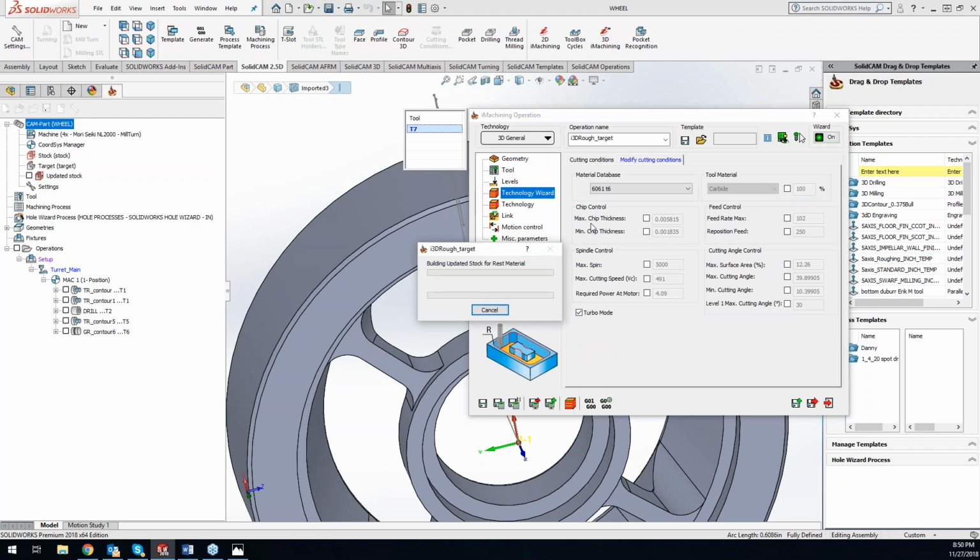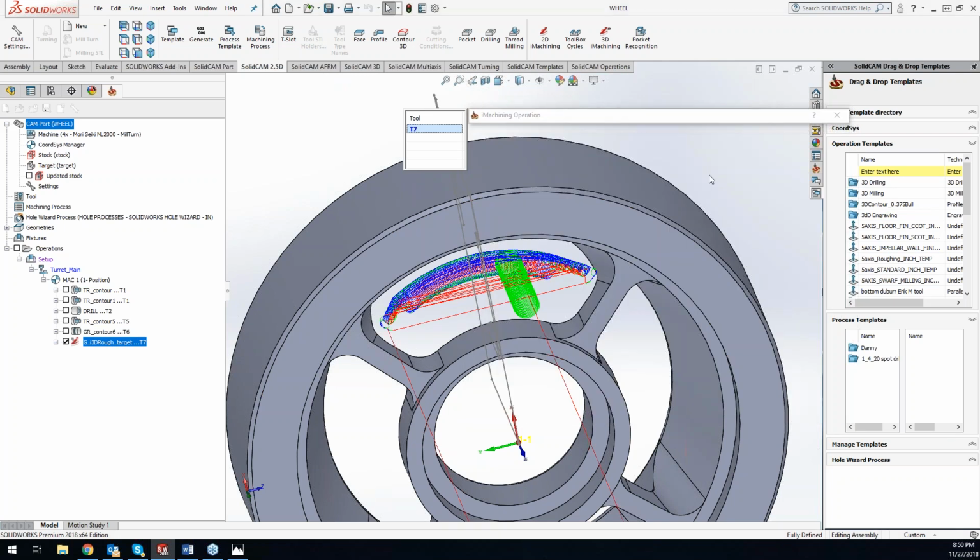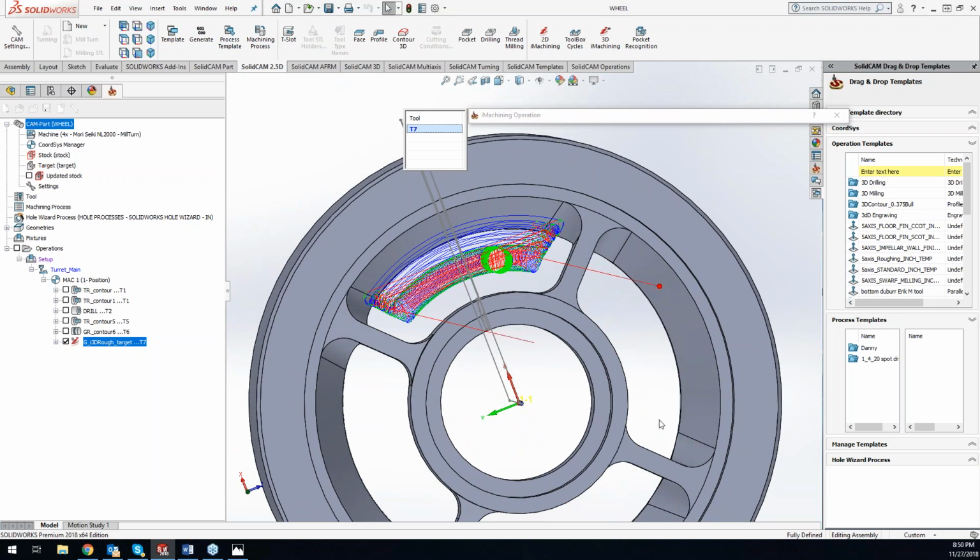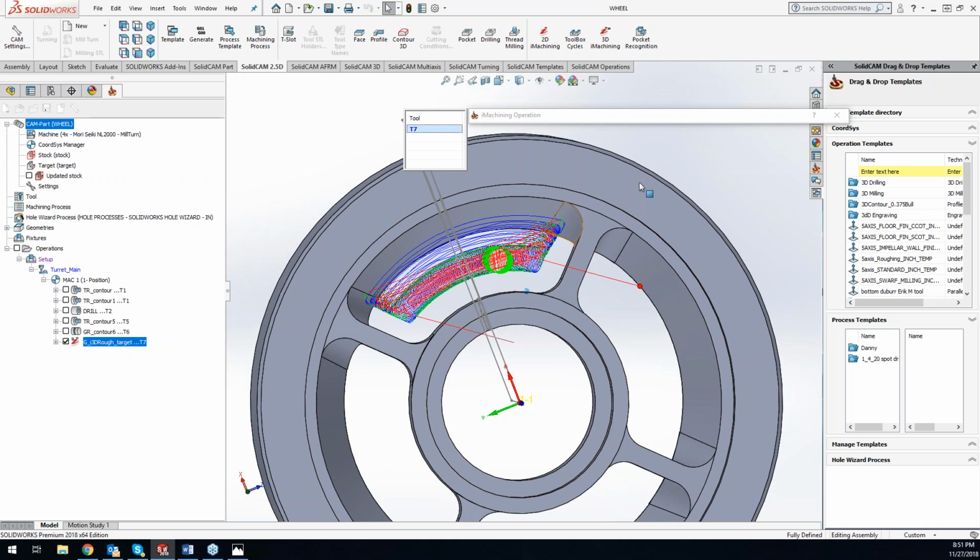Oh, forgot to grab the levels. Now, for geometry selection, you only selected the one pocket. Are you going to be transforming the other three pockets? Yep. Or are you doing those separately? Since we have geometry that is equally the same all the way around, my main focus right now is let's get this pocket done. And then once we have everything that we're looking for, we'll do a transform and transform it around to the other ones.